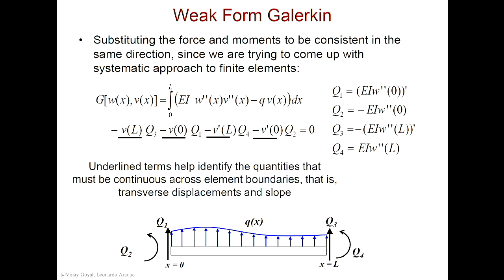Is that clear? Yes? Like when we had the heat transfer problem, the essential boundary condition was anything specified on temperature. Well, that tells me what needs to be continuous across element boundaries. The temperature needs to be continuous across element boundaries.